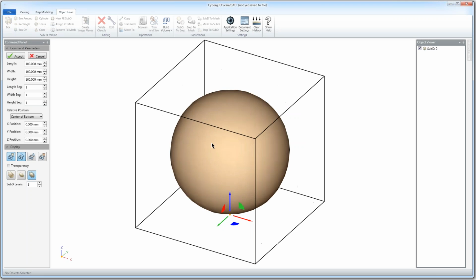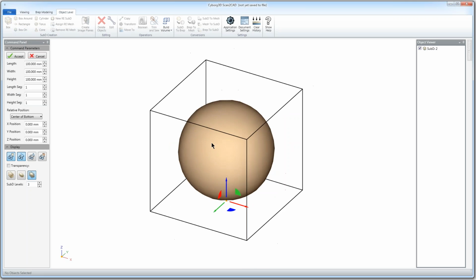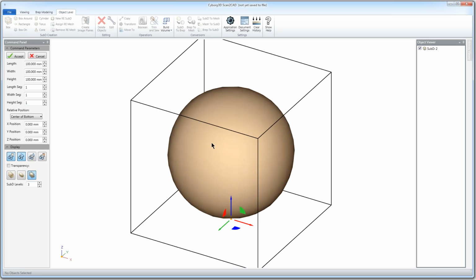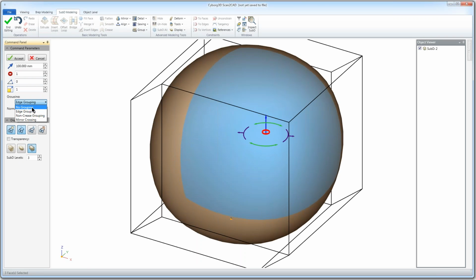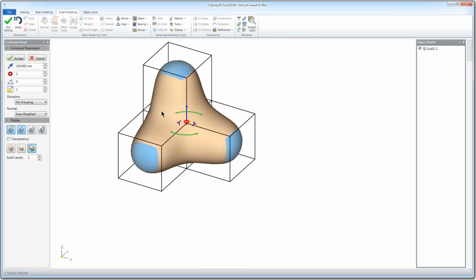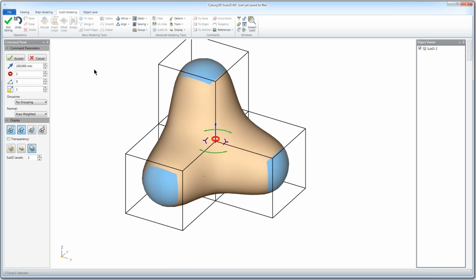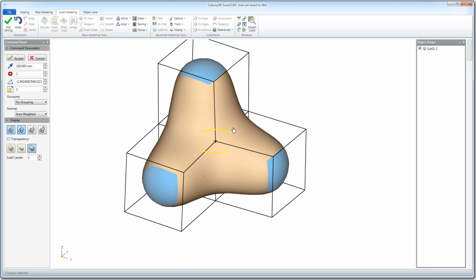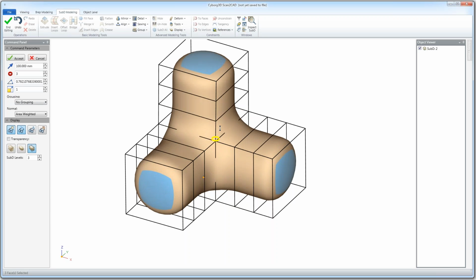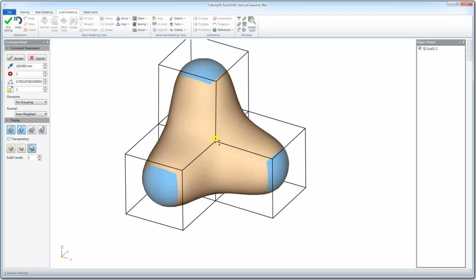Normally when people do subdivision, they do it one of two ways. The first way is they'll start with a box and then conform the box to the shape that they want. For example, you can grab the faces in the subdivision mode and extrude them, and we can control whether each face gets extruded individually or separately. We can control the twist angle, and also the number of subdivisions that occur.